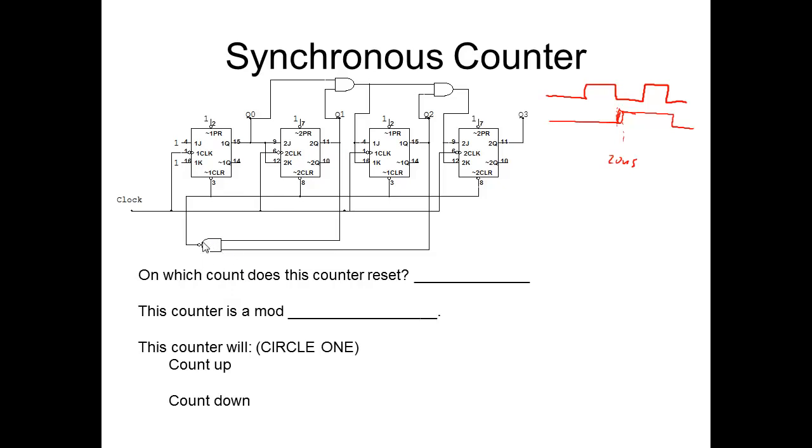Well, the best way to do this: the AND gate, or the NAND gate right here, when it has anything but two highs, let's say it has a 0, 1 on it. Well, a 0, 1 is going to give you a 1 out. A 1 is not going to clear these active low outputs, right? So it's going to operate normally. But as it's counting up, at some point in time, we're going to get two highs. When you get two highs there, this one goes to a low, which instantly resets these flip-flops, right? So you got lows on all these, and it's going to say, okay, I need to reset or clear these flip-flops and start all over again. So when are we getting these two highs? That's what we need to figure out.